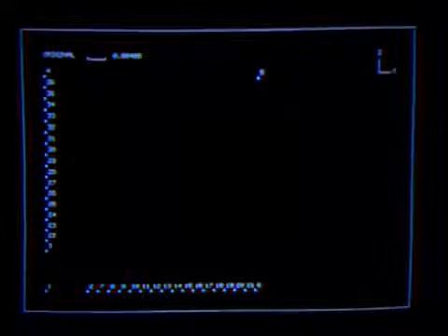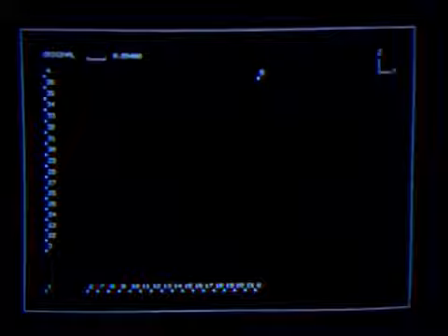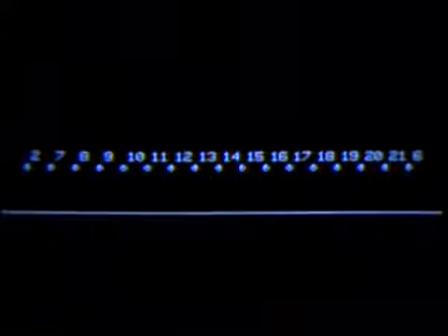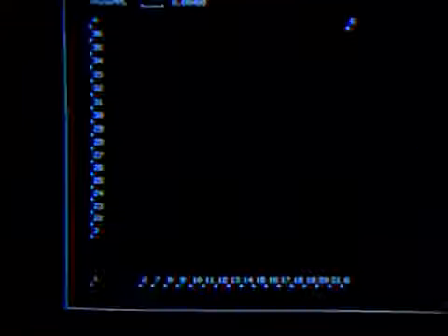And here you see the first set of generated nodes. Note that the nodal points have consecutive numbers along the vertical symmetry edge, except for the top and bottom nodes, numbers 3 and 4. Similarly for the horizontal symmetry edge. This would mean a large bandwidth unless we use a bandwidth minimizer. And we will do so, hence we are not concerned with the nodal point numbering used at this stage. Next we generate also the nodal points on the remaining edges of the quarter plate, and here they are.